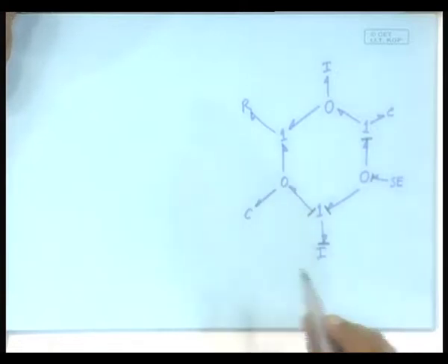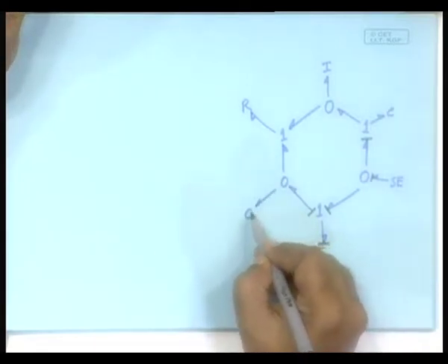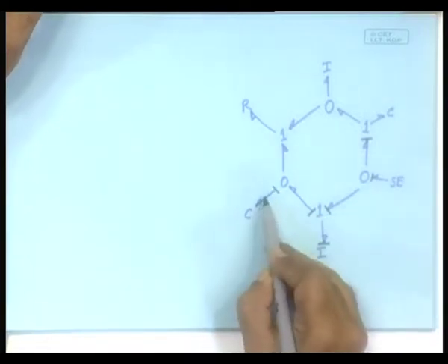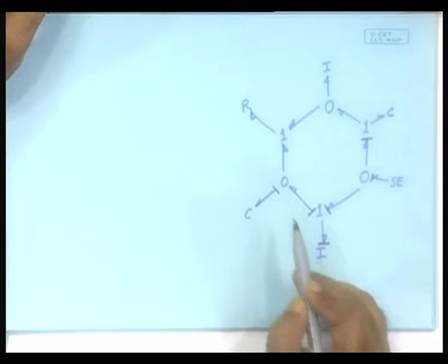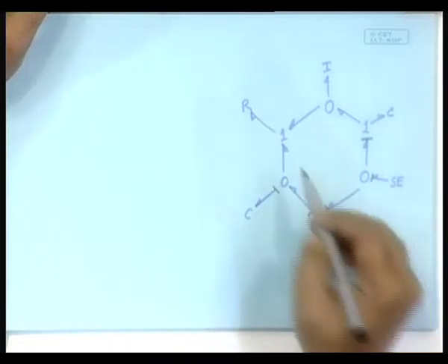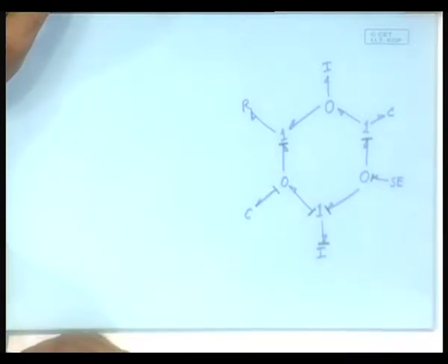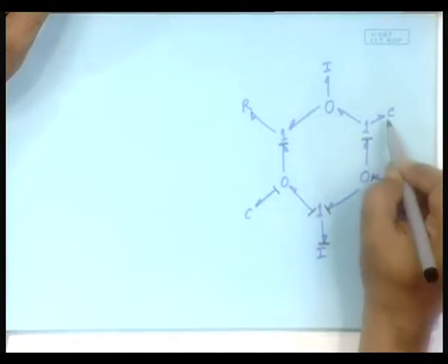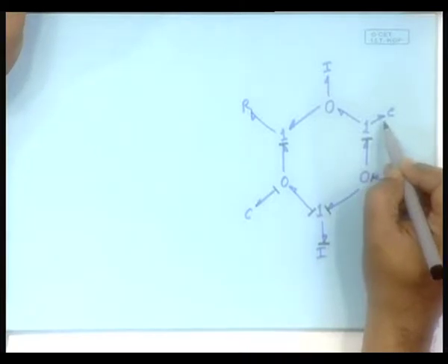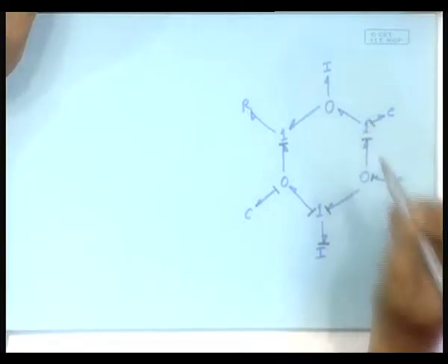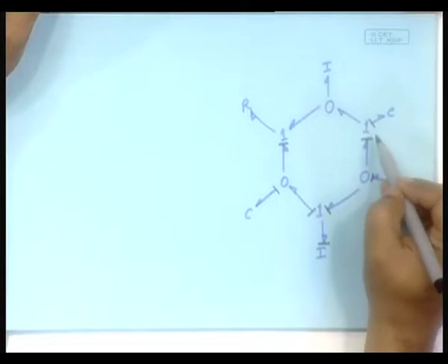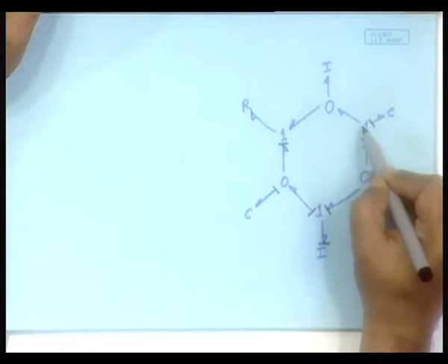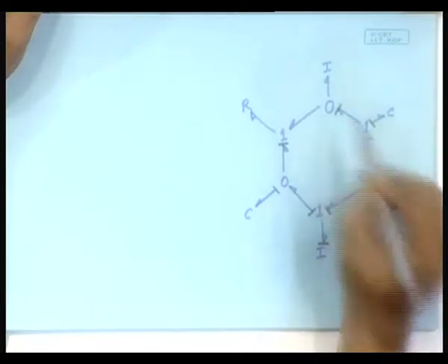As yet these are not causal. So, let me put the causality here. See, its integral causality is like this. So, it is giving the effort information into the 0 junction. The moment it gives, it has to be distributed like this. R we will leave out to do later. See, what kind of causality does it have? Its natural causality is like this. So, as yet these two are taking out the flow information, therefore, this bond must bring in the flow information like this.